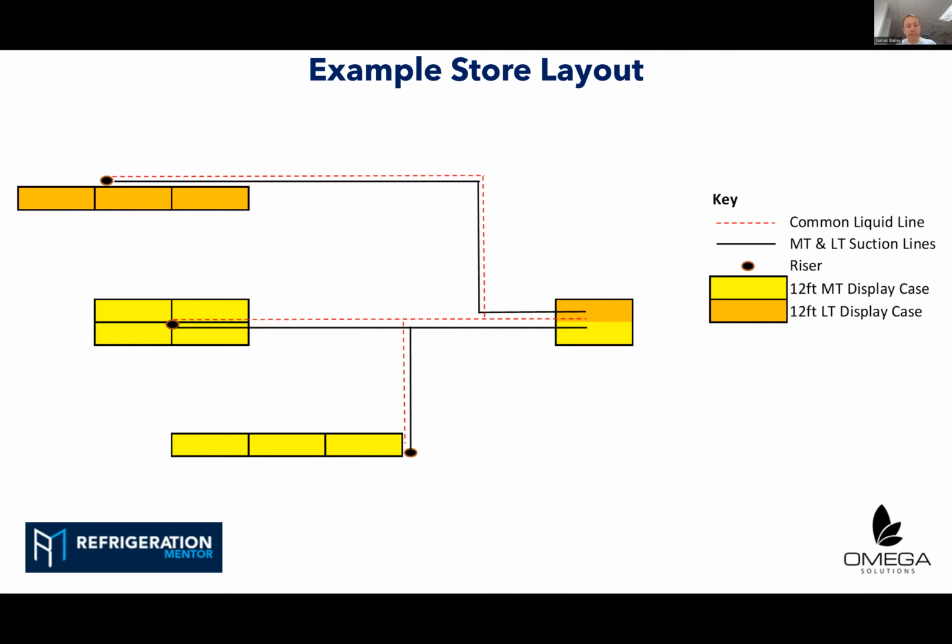Now, in the interest of time this evening, I'm sizing this system as a close coupled unit, so an assumption that the gas cooler is an integral part of the compressor rack and that the discharge and drain line is sized by the equipment OEM. Not necessarily the case in real life. We see many systems like that in the UK owing to space constraints. But obviously, the alternative is internal rack with external gas cooler. So that's something else I'll drop on everybody.